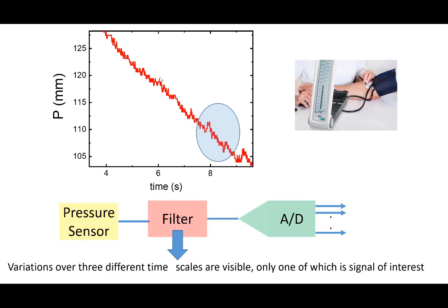All right, so what we are seeing is that, in order to interpret signals, what you may need to do is filter the signal or remove certain frequency components and maybe enhance certain frequency components. So when you want to do that electrically, you need a frequency sensitive element. Now, resistors are not frequency sensitive. A resistor responds instantaneously to every signal, V equal to IR. If V changes, I changes instantaneously. But capacitors and inductors don't respond instantaneously. They have a time response. So they are very useful for implementing filters. And so they become essential elements.